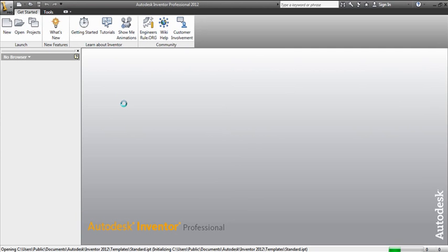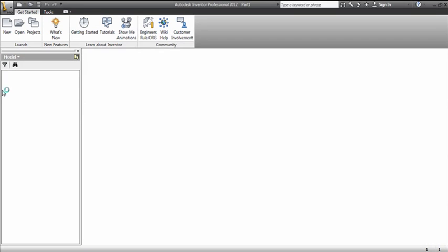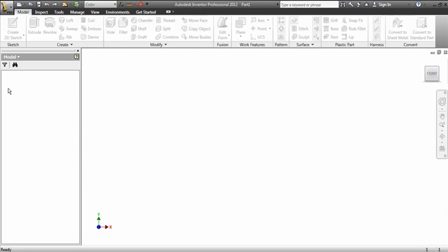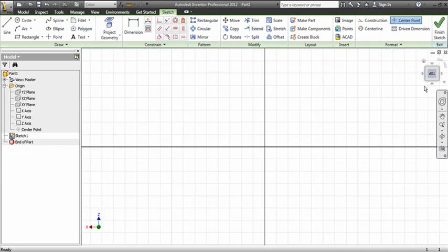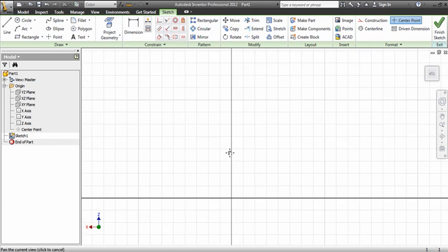Once your IPT is created, I'm going to create a sketch on the top plane. I'm going to click my origin, and I'm going to go to the XZ plane, and I'm going to hit New Sketch. And as usual, it turns this thing upside down so that the top is upside down. I'm actually going to keep it like that. I'm not going to turn it over, so make it so that your top is upside down. That way when we go to isometric view, the cow catcher will be facing us because of the way that we're going to create it.